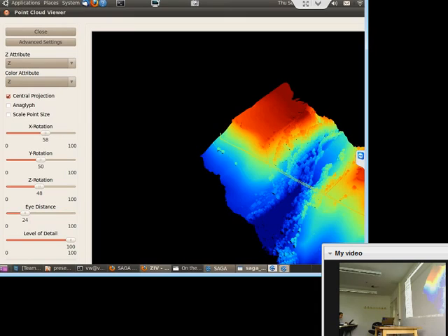I will save it as a SAGA point cloud, then you can load it directly. But how could I have the module? You need the liblas. It's a library which is used, and if you have it installed on your machine and you compile SAGA, then it's automatically detected and the module is compiled. If you have it downloaded as a package, then your package maintainer built it without LAS support. So you maybe can ask him to provide a version with LAS support. But it's a bit heavy.